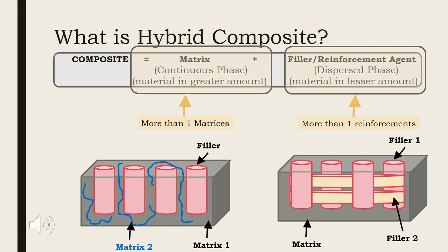The difference between monocomposite and hybrid composite is a critical question. Monocomposites use one reinforcing agent and one matrix, whereas hybrid composites are second generation composites that use more than one type, shape and size of reinforcing agents or matrices to get excellent properties.